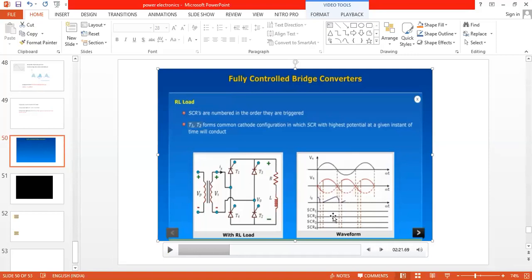So here you can see input voltage is 0 at omega t equal to 180. Output voltage is also 0, but current is maximum because we are using a large value of inductor. Current value is maximum here. And next, the current flowing through the inductor will never be equal to 0 at omega t equal to 180. This is the most important objective type question.